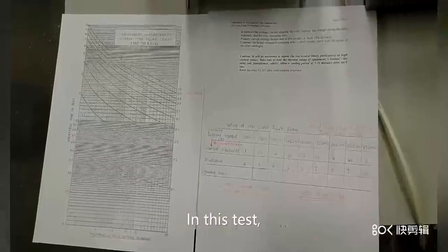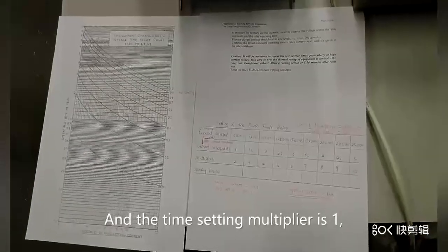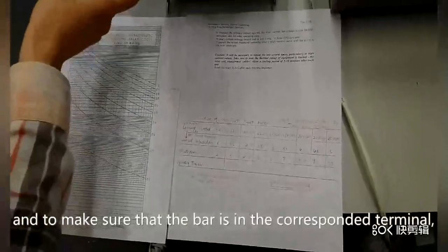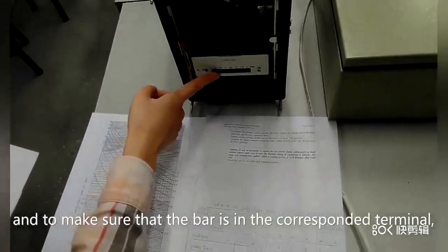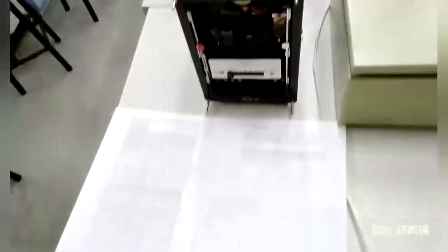In this test, the relay current is set to 105 amperes and the time multiplier is 1. And make sure the bar is in the corresponding slot and the timer is set to 1.